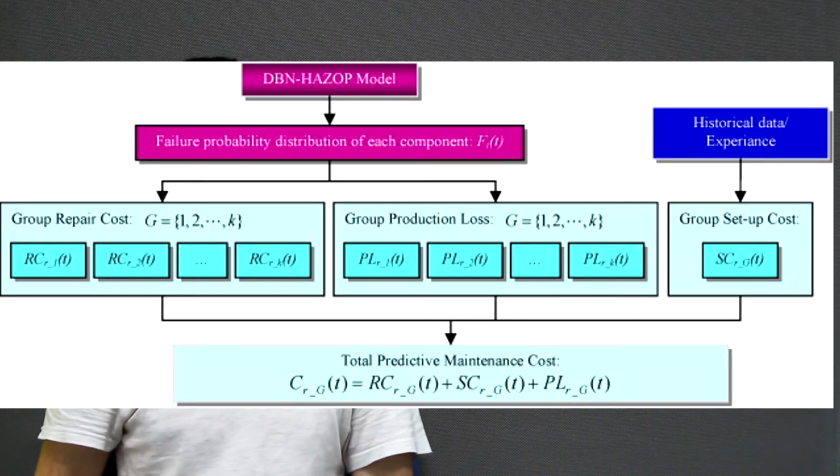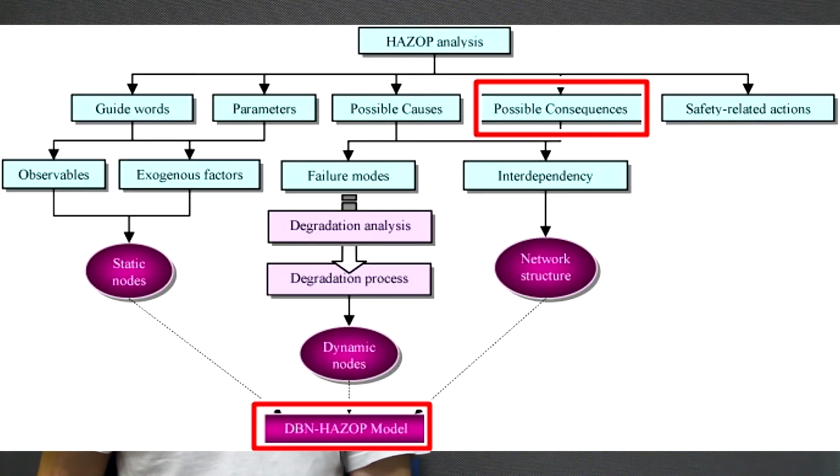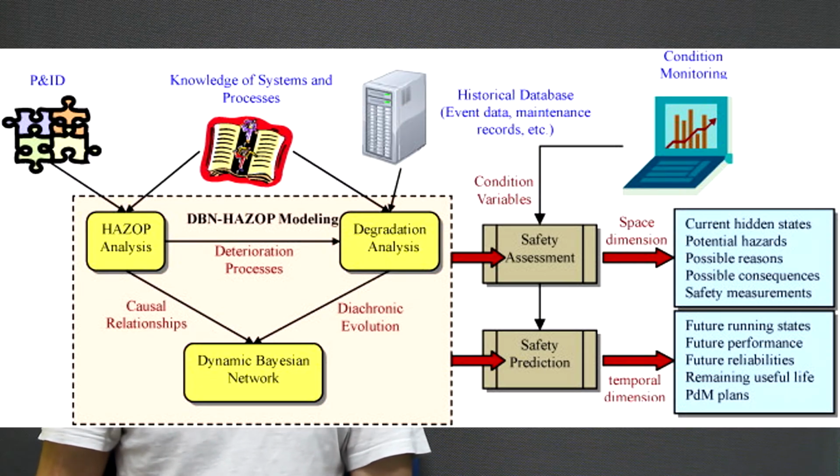This model is able to obtain data from the system for analysis and predict future failure by inference, rather than directly observing causes before failure occurs. In other words, DBN is able to improve the database by learning the possible consequences and mistakes that could be made by the current plant design. By doing so, algorithmic thinking technology by computers on HAZOP could be the solution to overcome incomplete HAZOP analysis.